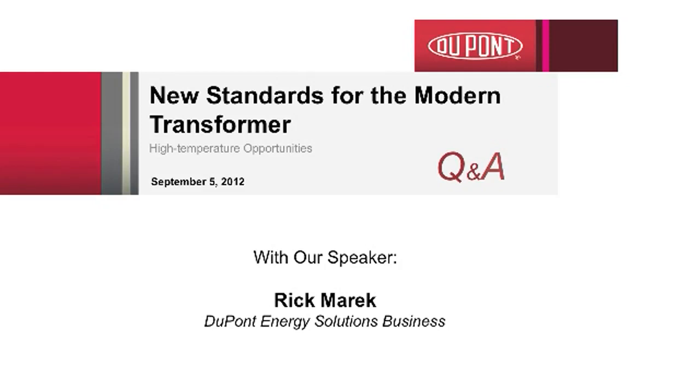Someone from our audience is asking, apart from Nomex and Kapton, are there any other materials that could be used for high-temperature liquid immersed transformers? Well, there aren't very many. That is for sure. None others that I can think of. In some cases, polyester glass is acceptable in some mechanical applications, but not a good choice for areas that see dielectric stress.